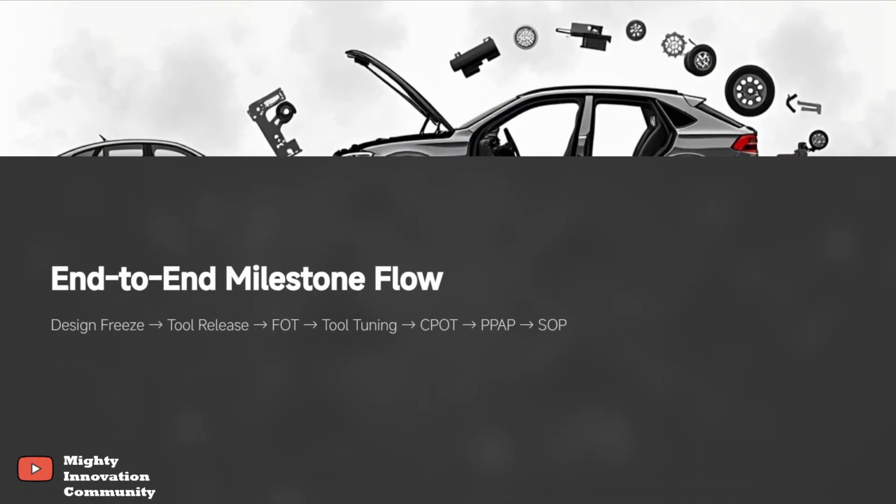So in summary, if you remember only one flow, remember this. It starts with design freeze, then tooling release, then FOT, then tool tuning happens, then part approval or CPOT, then the PPAP and the SOP. These milestones decide whether a part launches smoothly or becomes a constant problem. So now when you hear these terms, you actually know what's happening behind the scenes.